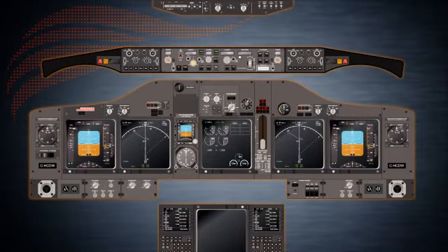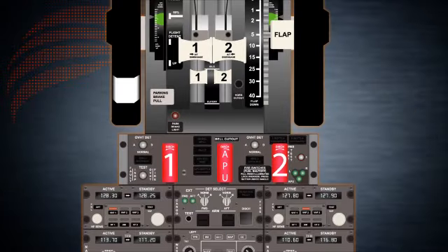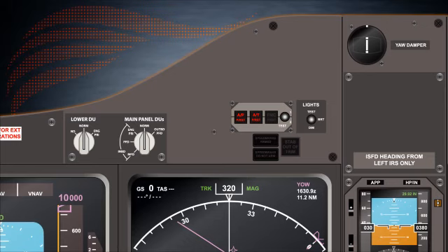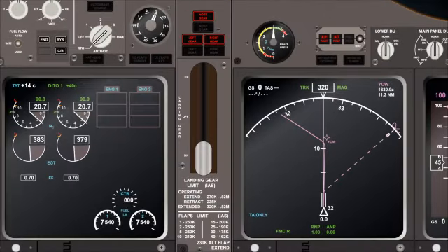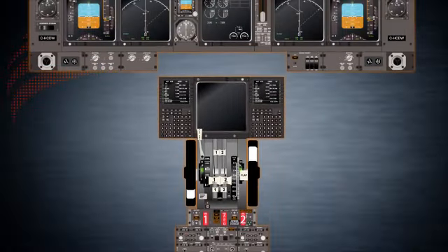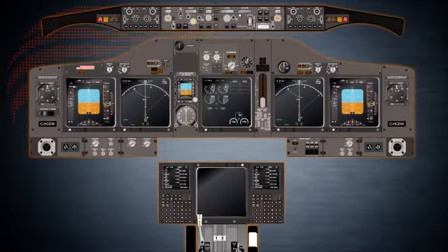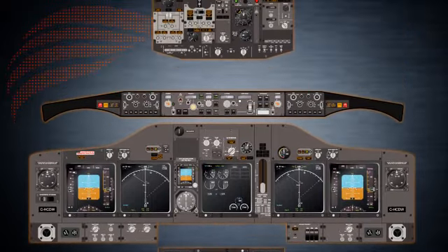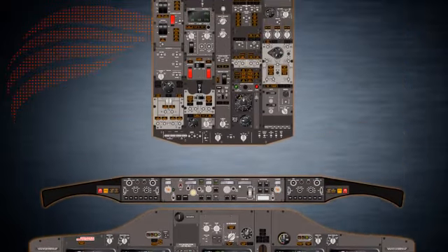Different colors are reserved for different categories of conditions on the 737 flight deck. Red warning lights indicate conditions which require the immediate attention of the flight crew. Such lights include engine, wheel well, cargo or APU fires, autopilot or auto throttle disconnects, and landing gear unsafe conditions. Amber caution lights indicate conditions which require timely but not necessarily urgent attention of the flight crew, and there are amber caution lights scattered throughout the flight deck.